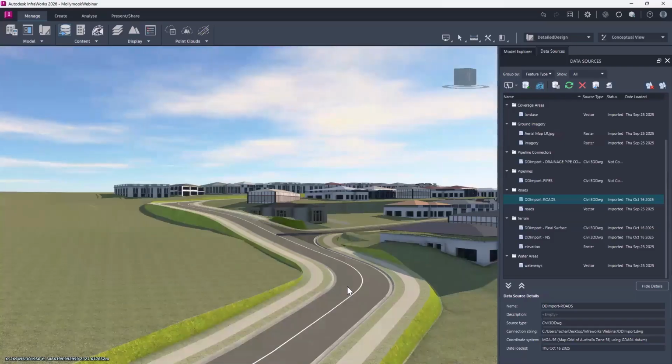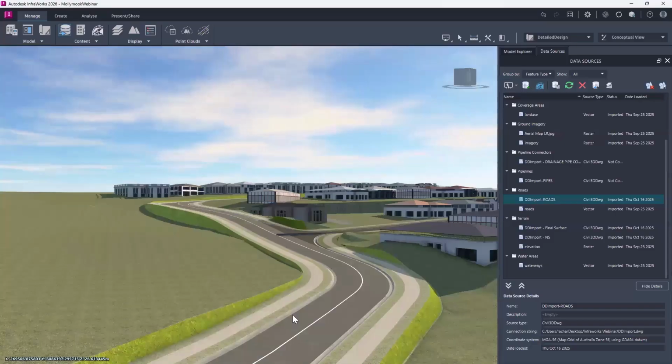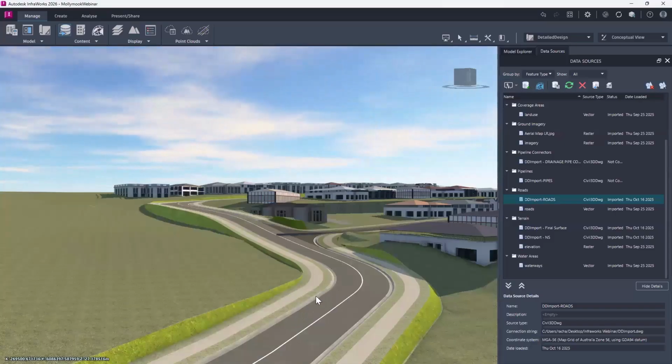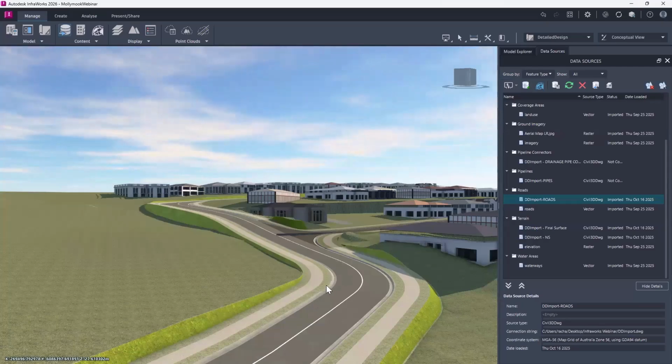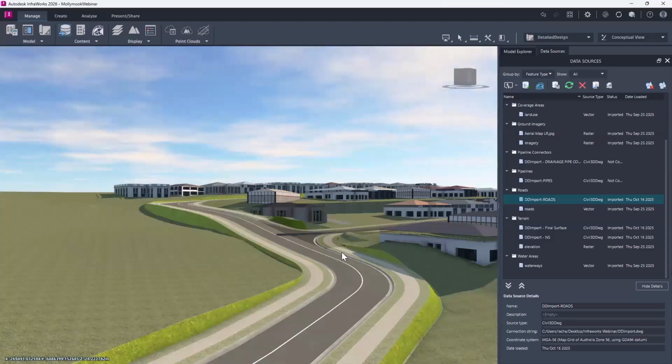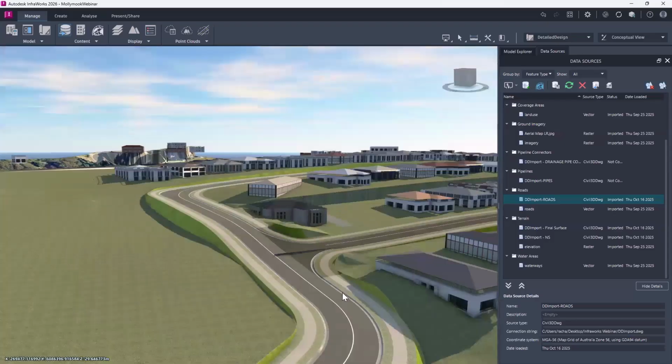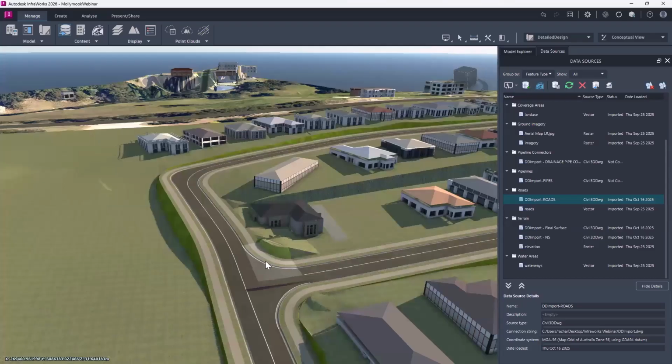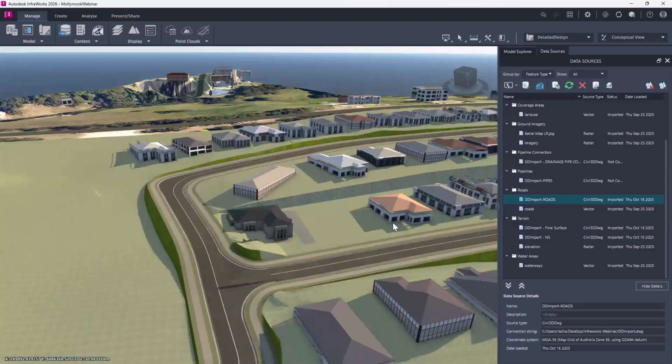And most of the different links have automatically figured out, like between the center line and the lip of the curb has come in with asphalt, and then I've got my concrete curb, my footpath, and I changed it so that the nature strip would come in as grass as well. And all of my curb returns have come in nicely as well.